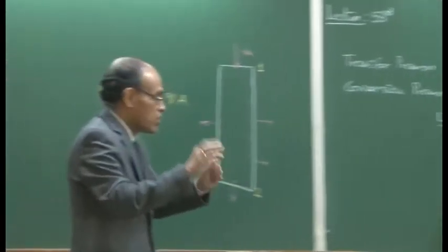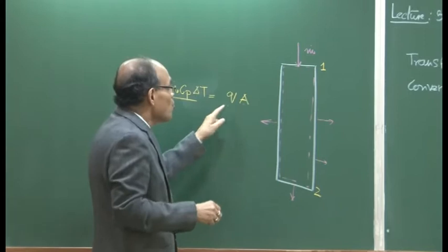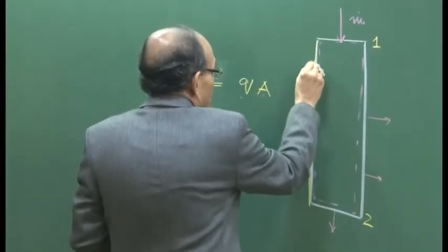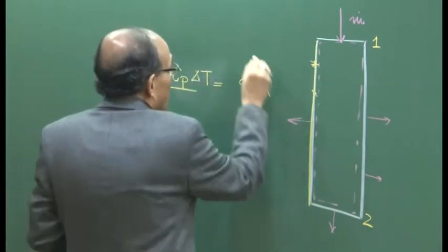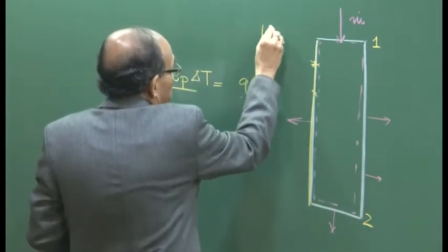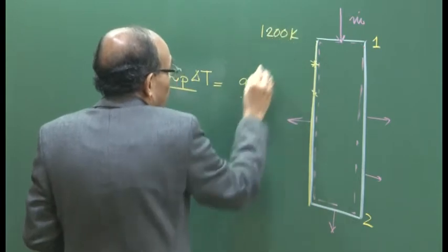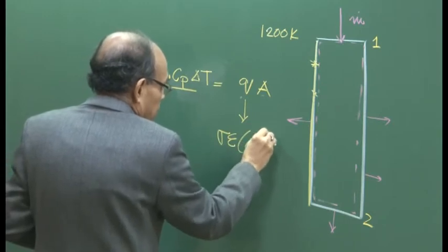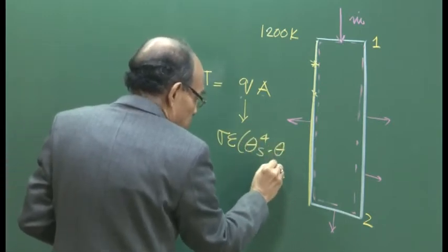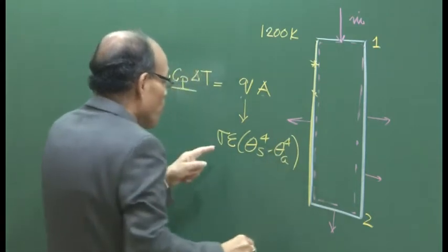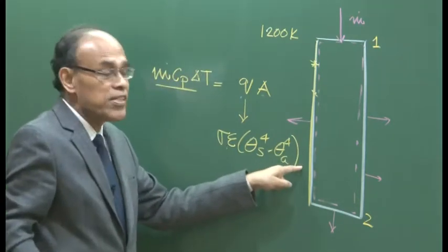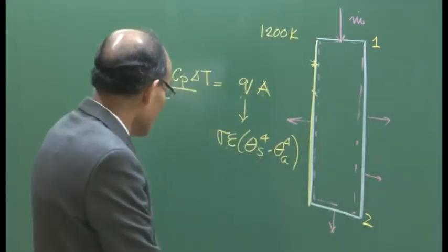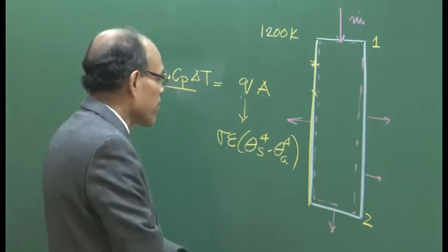So, therefore, the shroud surface is exposed to different kinds of thermal environment, but if you ignore this for the time being and you assume that a constant temperature prevails at the shroud surface, which may be based on measurements, these shroud temperatures could be somewhere around 1200 Kelvin. So, you should be able to calculate the radiation flux, convection flux is going to be less important, and therefore, if you know the emissivity of the refractory surfaces, and these shrouds are made out of mostly magnesia and alumina, they are the kind of refractories that we have.